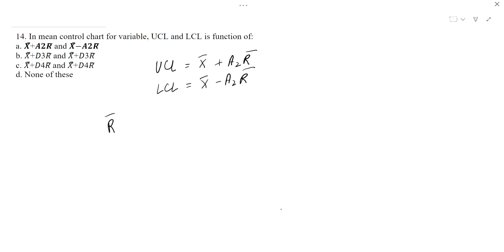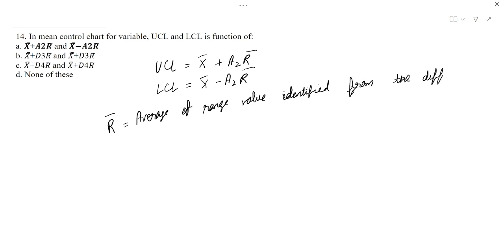Here R bar is equal to the average of the range values identified from the different samples which have been taken from the lot.